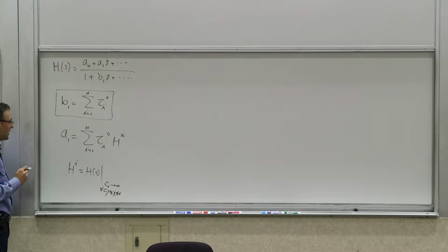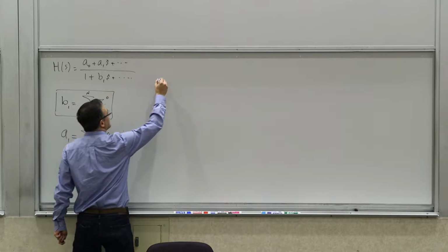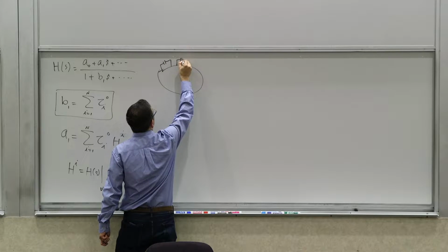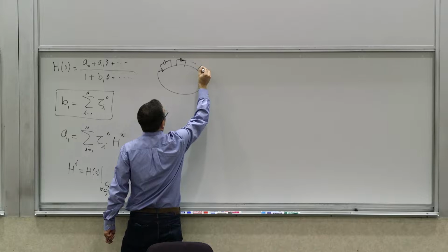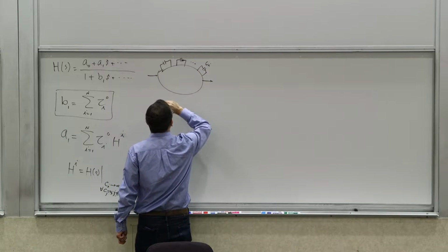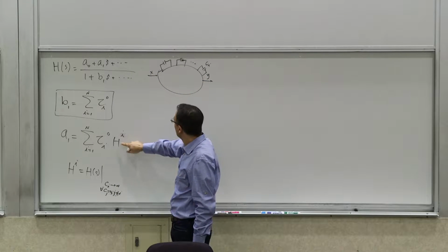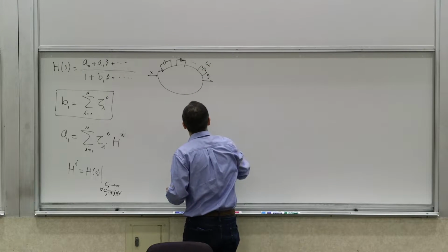Right? So in other words, if you have a system, let's say this bubble, and to make it simple, let's just think about the capacitors, and the same thing applies to inductors. So you have a bunch of capacitors, and then this is your Ci. When you're trying to determine the transfer constant Hi, you say, I set Ci to infinity.